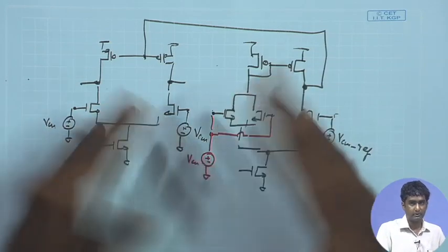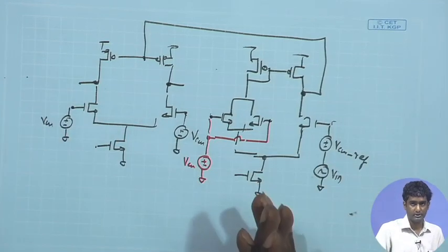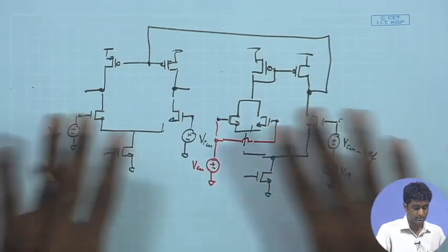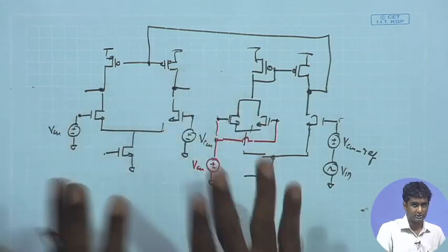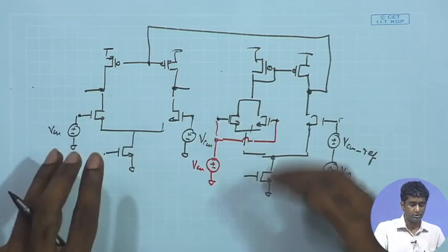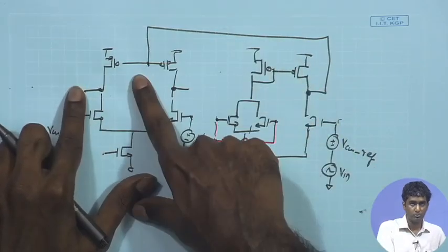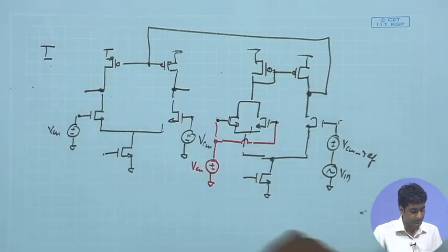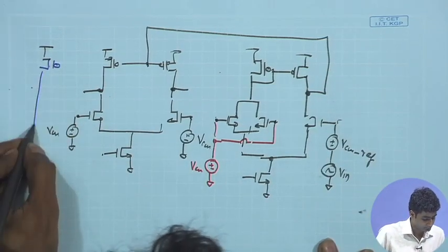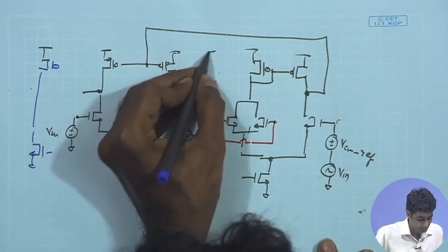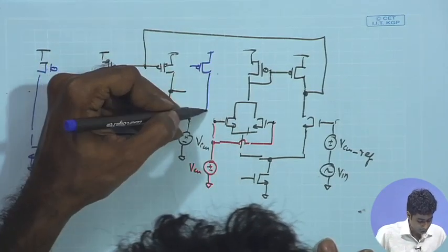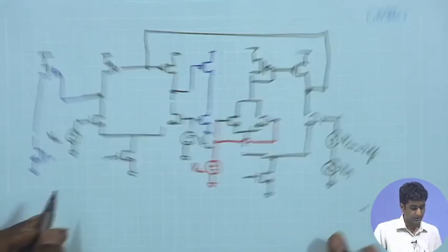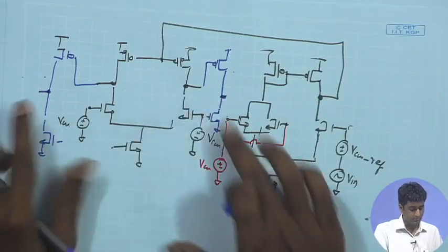Likewise, if we do the common mode feedback for the whole two stage, there also similar biasing conditions need to be checked and ensure that the overall error amplifier and the two stages are maintaining the same biasing scheme. And suppose you are using the same single loop for the common mode feedback, then overall the scheme remains same. Only thing is, after that you will have another two stages added, which are the common source stage, so these are the additional stages which get added, and your output, you are taking it from these 2 points.